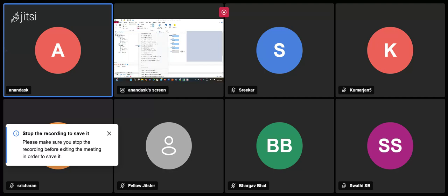Now we will try to add this interactive generator. It is just like this, and then we need to configure it. Here we can add frame from database, add CAN FD frame, and add CAN frame. So this is the CAN frame, this is the CAN FD frame, and this is from database. I think we don't have any database.